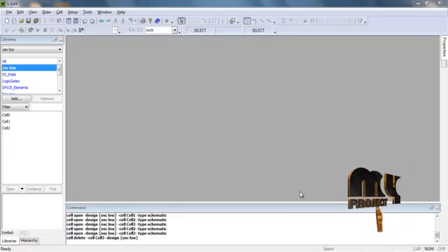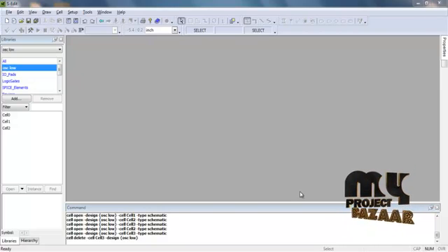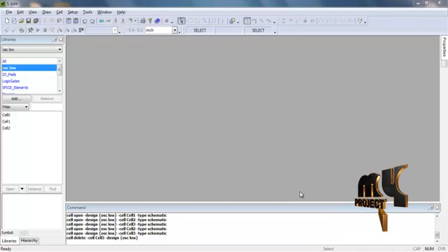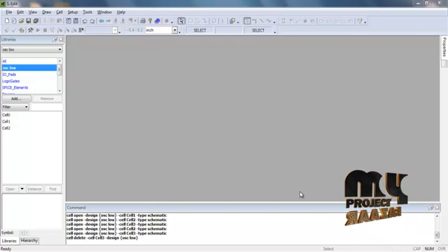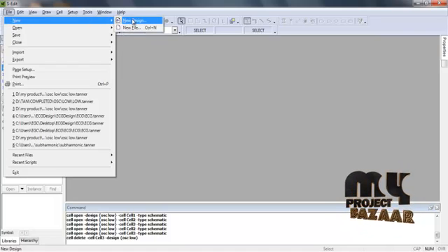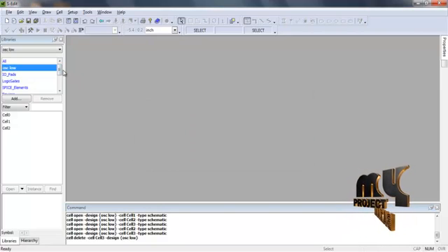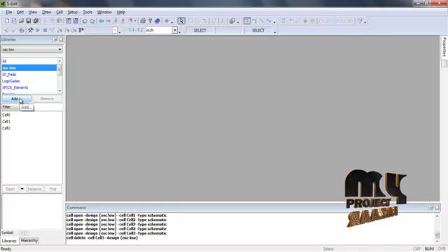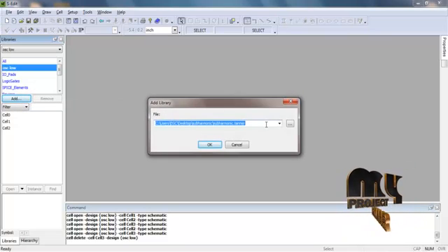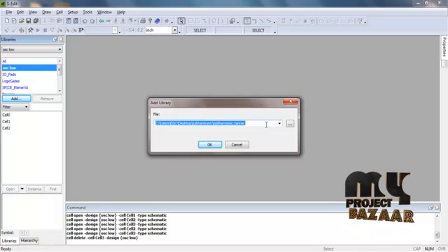Now we are going to discuss about the running procedure of our product. Our product can be implemented by using a Tanner EDA tool 13.0 version. Now double click to open the tool window to create a new design using file option. File to create a new design. In desired path, allot the design name. After creating the design, now we are going to add the library files from this add option. Click add to select the desired path of library files to add the libraries of Tanner EDA.